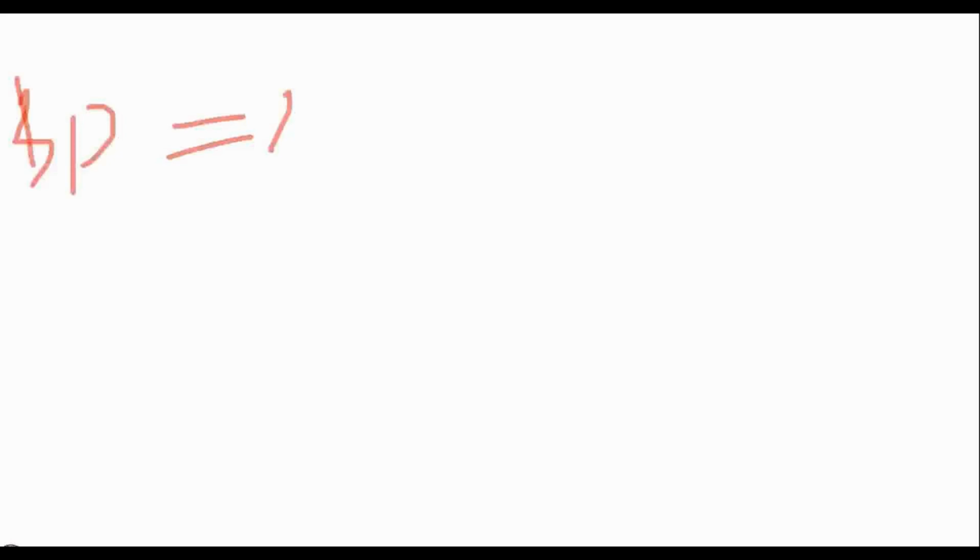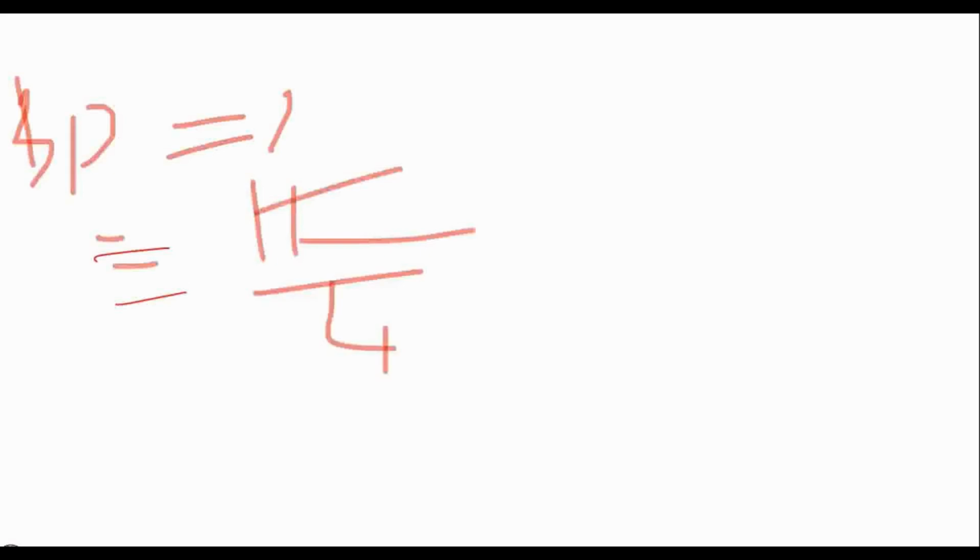Try to read fast now because the time is also running. So first we have to calculate the swept volume. Swept volume is nothing but pi by 4 d square L, which is the bore diameter into the length. So you get a swept volume.